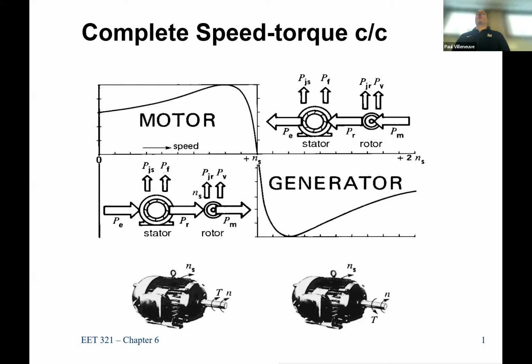It's the induced torque. So when I steal electrical power out, that has to act like an equivalent torque, right? It's power. Power equals torque times omega. So I'm taking electrical power out. That means I have to take some torque and remove that. And if I'm driving it externally in a clockwise direction, my electrical power has to be going out. And if they were both going in the same direction, the unit would continue to speed up. This is an induced torque. This has to be in the opposite direction to counterbalance the applied torque from the mechanical shaft. So induced torque is always in the opposite direction of the applied torque. Otherwise, it will just continue to speed up.